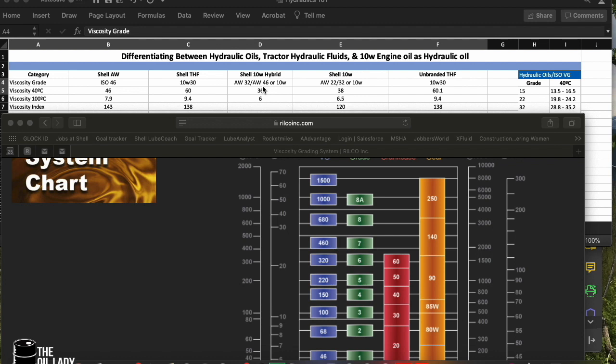Now, again, all application specific, but lubricants in this instance are generally very forgiving. If we're talking about general construction and heavy equipment, you are pretty darn safe using any one of these products when it comes to the viscosity. They are all pretty close. My rule of thumb that I tell my construction customers is you are safe going above or below one viscosity grade.